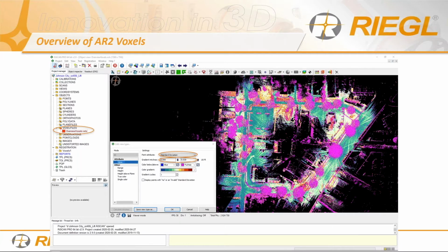And hopefully I get to show you this project if I have time. All this point cloud, this project was done in the rain. We scanned it when rain and snow was coming down, so there's a bunch of noise in this data from the rain. But nevertheless, the surfaces that you want to concentrate on are the roads and the buildings. You can see here, the registration is really good. This is just the initial overall registration before MSA2. This is just right after AR2, automatic registration 2.